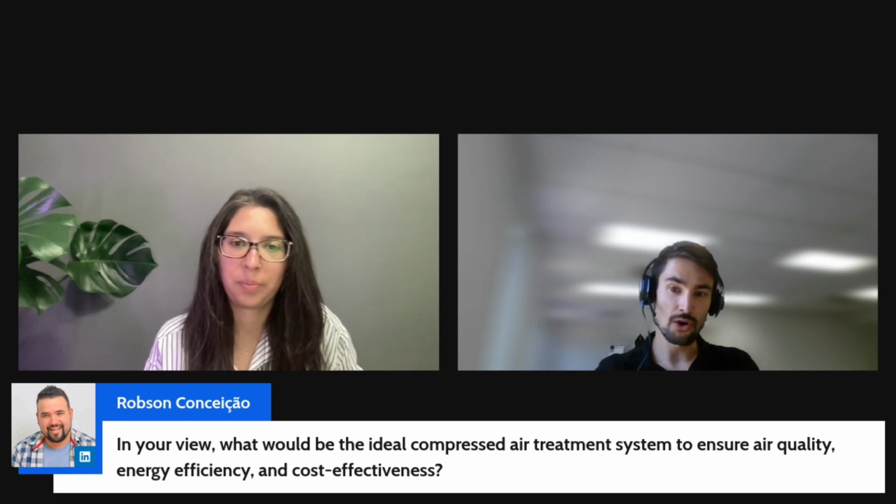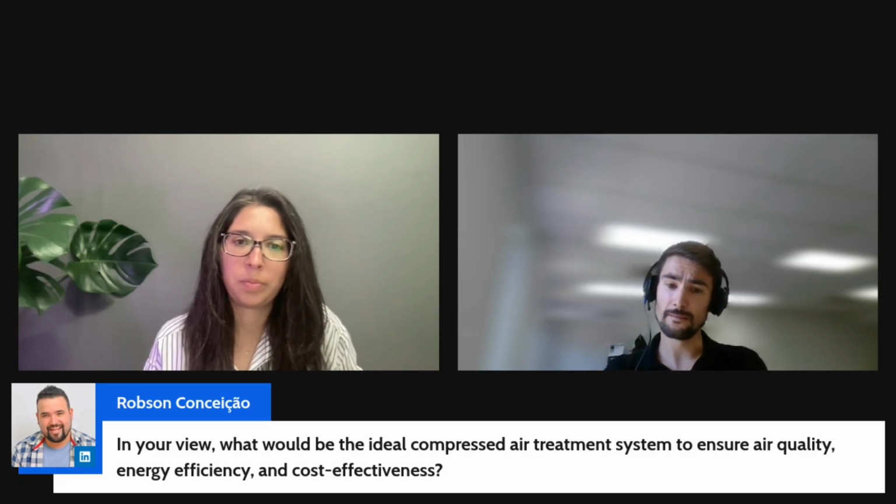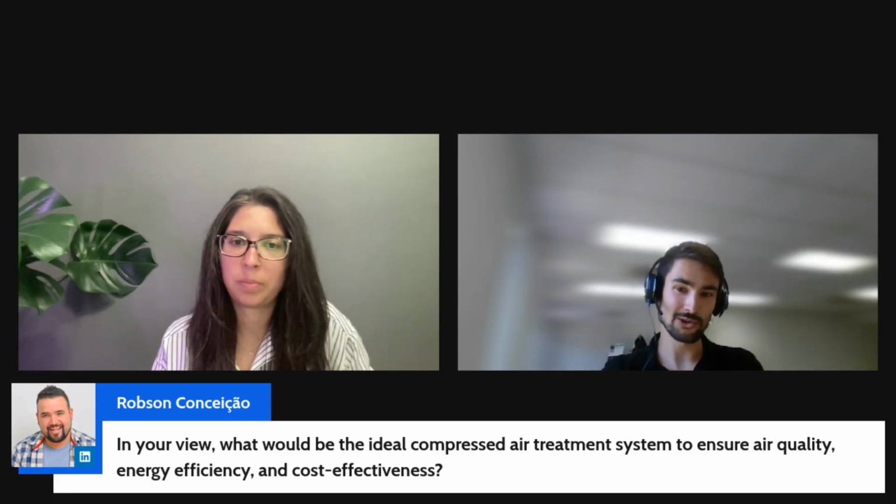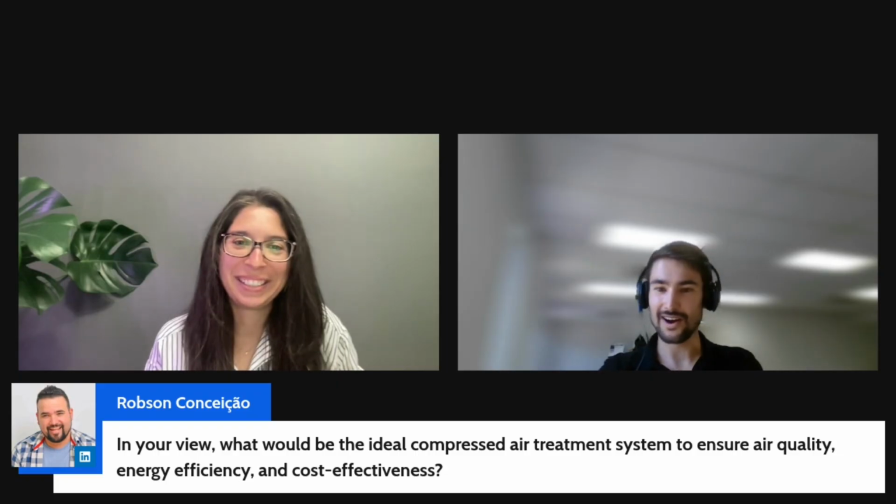So you want all of that done. You will have your oil-free systems. You could also use an activated carbon tower. And then you want to have a point of use sterile filter that can be sterilized, that catches any possible contaminants. So it really depends if you have that or if you're running a 5 micron filter and a refrigerated dryer. There's no one size fits all for compressed air treatment.